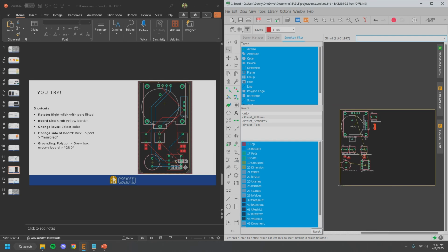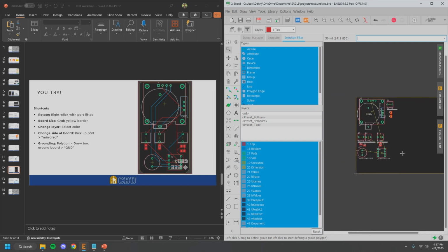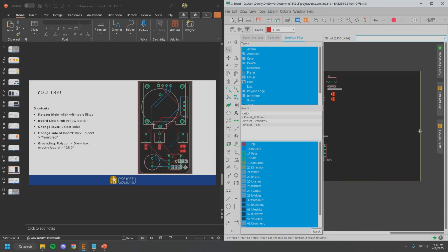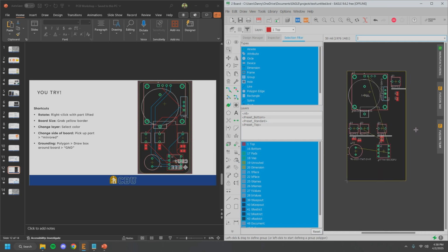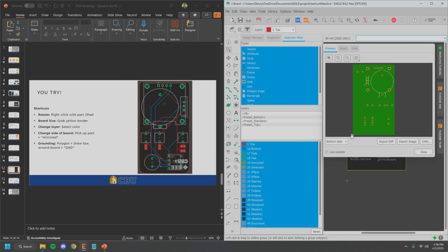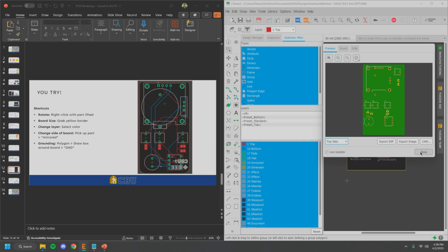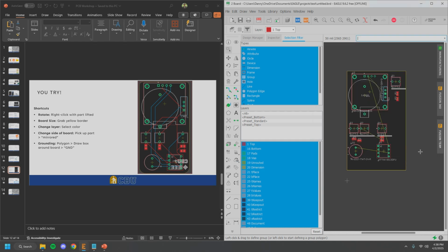And what you'll notice comparatively to the default board is that the size of this board is currently just in its default shape. So what you're going to want to explain to students is that if you drag this yellow side, this is the physical dimension of our board. By sliding this over, I am shrinking it, so it's running down the cost of our actual manufacturing cost. And it's just making it a lot cleaner because this is a mini gaming PCB. We don't want to have a lot of dead space that we're not using.